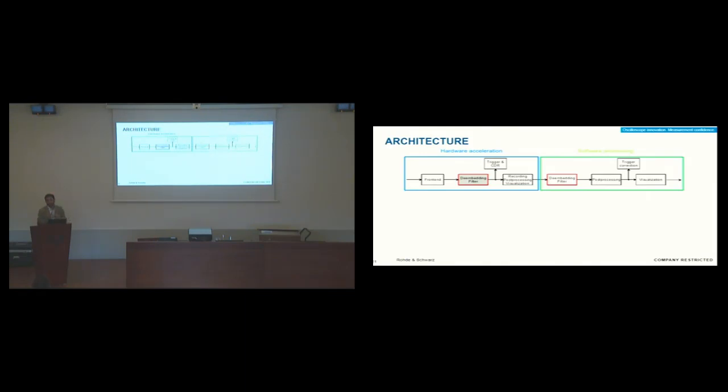But there is also a second impact: the signal we are watching in the oscilloscope is not the signal we are triggering on, because the trigger is done before, in hardware. So we trigger on the signal which is not corrected, then we correct the signal. So we have something on the screen, but that is not really the signal we are triggering on.